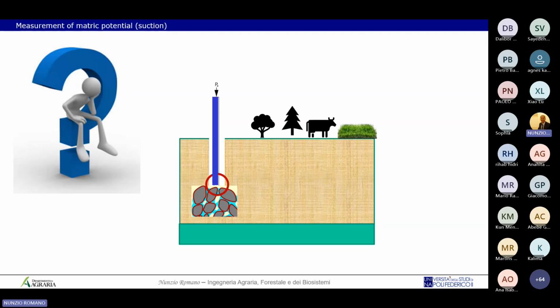So everything is positive in the tube. And what is the sign of the pressure in the soil? The soil is under suction. The water, the matric pressure, is negative. So negative is less than positive, and this is why you lose water very abruptly.